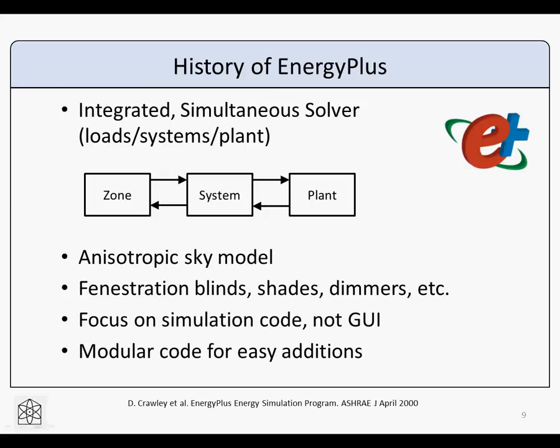EnergyPlus focuses on the simulation code, and it was built initially as sort of a simulation solver. It was not meant to be a graphical user interface, and so that's why OpenStudio was developed for that. And there's a few other interfaces for EnergyPlus. DesignBuilder is a common one, and Simergy is another pretty common one. So keep a lookout for those if you're ever doing energy simulation in the future, and you come across those, you'll know that that's EnergyPlus in the background. The other nice thing about EnergyPlus is it's sort of modular code, and that was recently converted from Fortran to C++, so it's more approachable now.